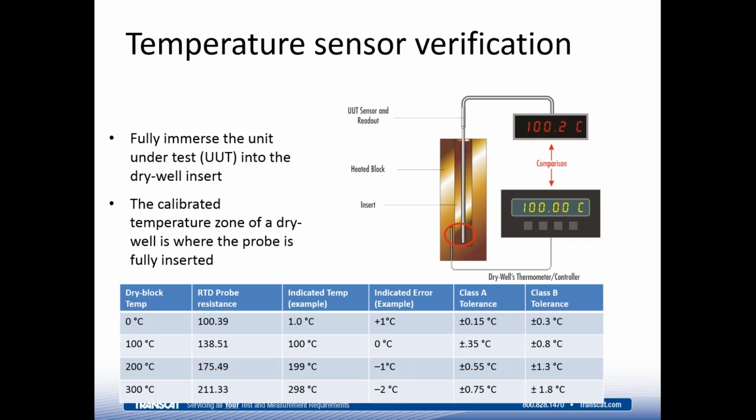So this is an example of how you go about thinking through whether the calibration passed or failed. Now that's for a verification. That's the kind of sensor that maybe you don't provide any special calibration coefficients for. You just want to see if the Class A probe or Class B probe is in or out of tolerance, and you toss it if it's out and replace it.